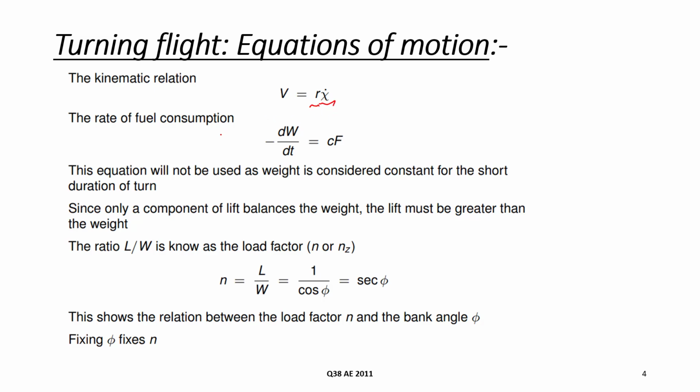And the rate of fuel consumption can be written as minus dW by dt equal to Cf. We also define the load factor n equal to L by W.